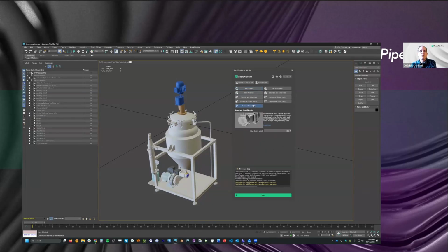There are other things too. Remove small parts, for example. This is in scene units. So basically at 0.01, if the scene unit is 1 meter, then it's going to pull out anything that's smaller than 100th of a meter, which is a centimeter, right? Is that right? Yeah, a tenth of a meter is a decimeter. So if you want to say remove anything smaller than 1 centimeter, then that's what you can do. So those things are all relative to the scale of the scene, but we don't really have any limits in terms of how large the scene can get.